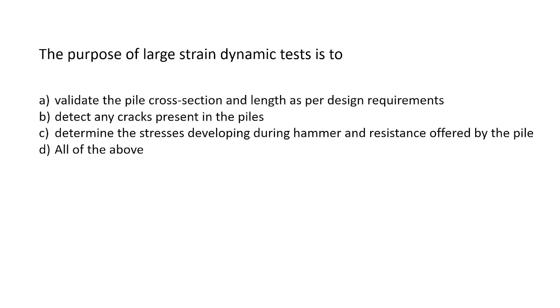So the question is, the purpose of high strain dynamic tests is to validate the pile cross section and length as per the design requirements, detect any cracks present in the piles, determine the stresses developing during the hammer and resistance offered by the pile, or all of the above. Anyone? C will be the answer. High strain dynamic testing determines the stresses developing during hammer and resistance offered by the pile. Yeah, correct.